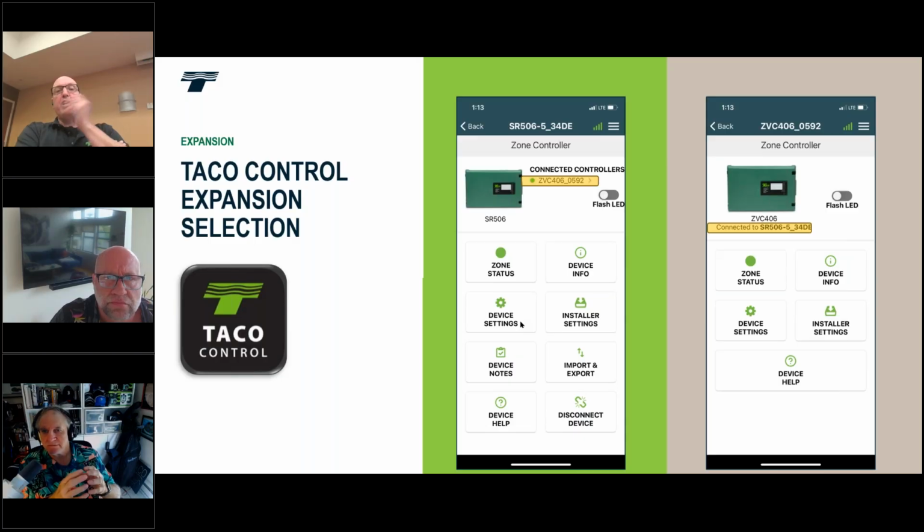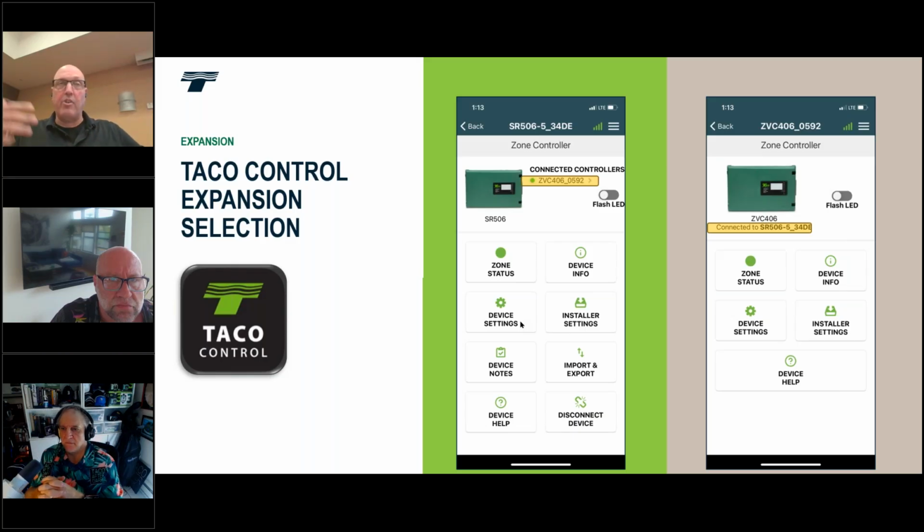From the dash 4s and the dash 5, there's a yes and no answer to that. We will show you how to wire it in our new wiring guide, which is coming up in a couple. No, we don't have the Bluetooth built into it, but we can make the two controls work, yes. So if you've got an older project that had two dash 4s and somebody let the smoke out of an older dash 4, yes, you can put a dash 5 in there, and we show you how to make that work.